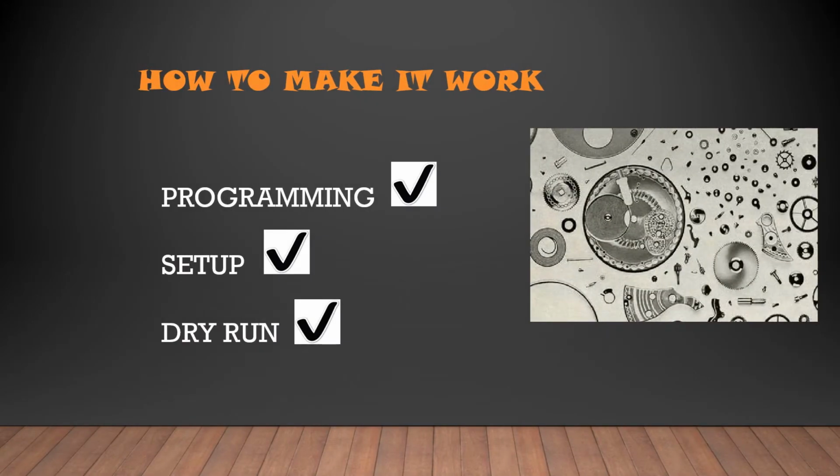All right, how to make it work. First of all, the programming, very important. We need to understand and learn how to effectively program the workpiece. Number 2, we need a defined and well thought out setup of how we're going to configure our tool stations. And number 3, we always want to dry run this particular program to make sure that our timing and our waiting codes are in the proper place.